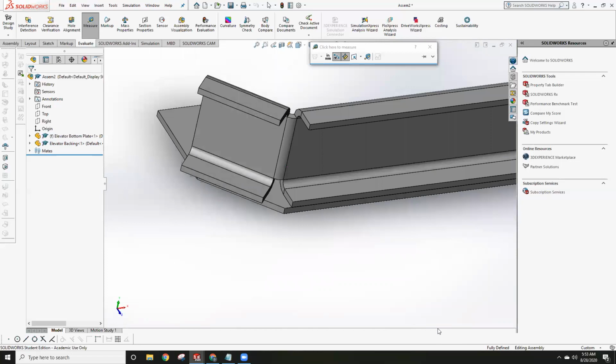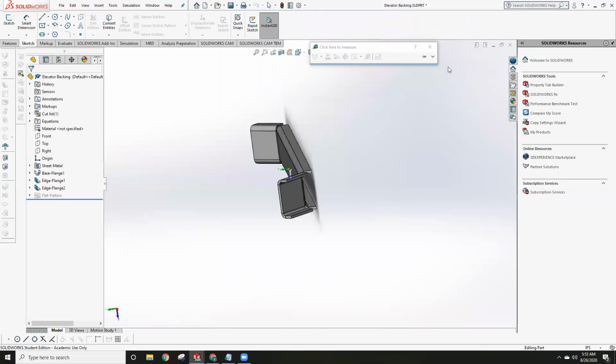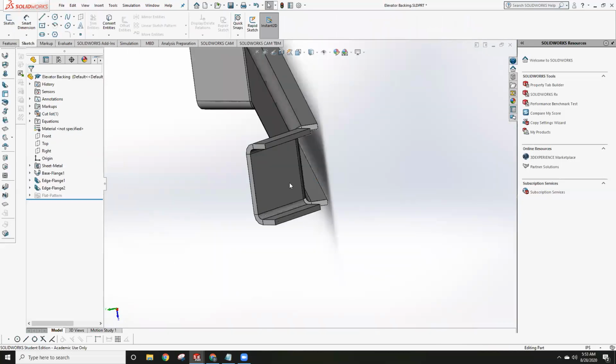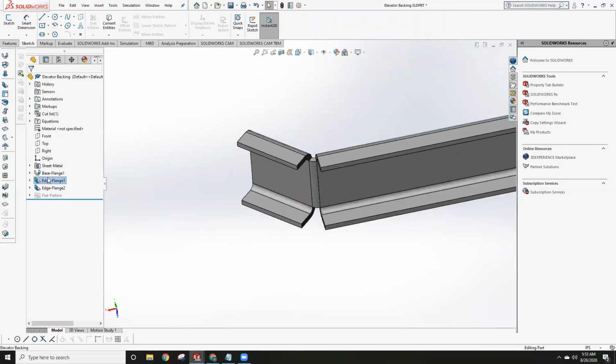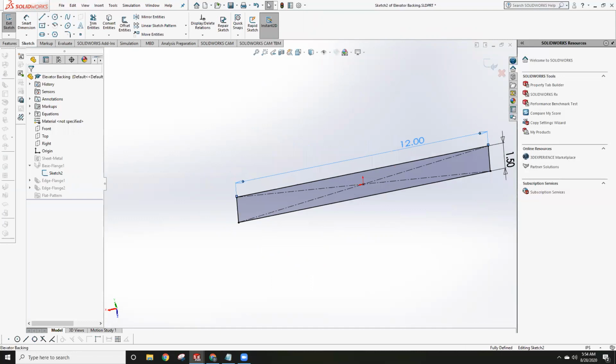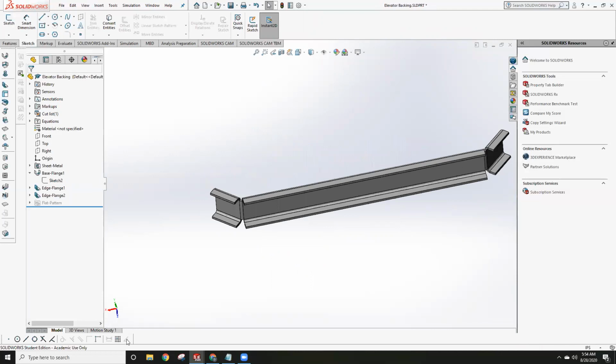So there is not a good solution to this. The good solution is don't do 45-degree bends. The sucky solution to this is find the difference, subtract it from 12. So minus 0.1313708. And you know what? That's good enough for the CAD-a-thon. That's the only time I'm going to be using 45-degree bends.